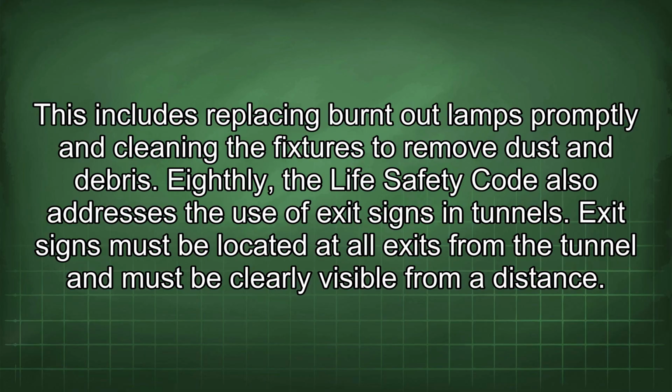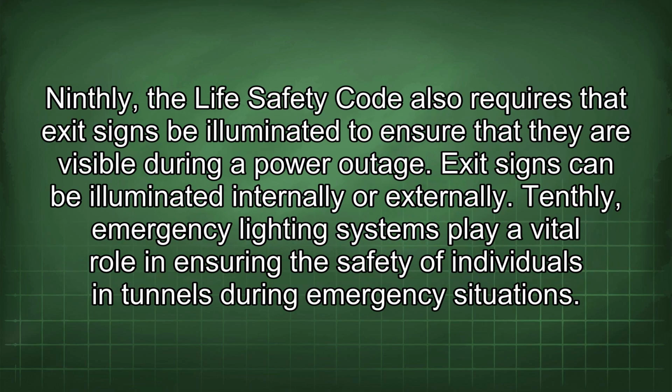Eighthly, the Life Safety Code also addresses the use of exit signs in tunnels. Exit signs must be located at all exits from the tunnel and must be clearly visible from a distance. Ninthly, the Life Safety Code also requires that exit signs be illuminated to ensure that they are visible during a power outage. Exit signs can be illuminated internally or externally.